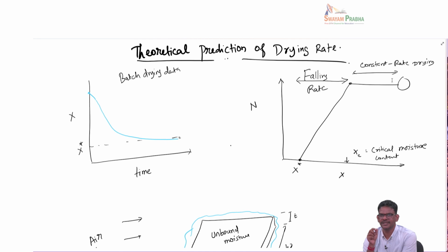On the other hand, if you are starting with a very cold object, then the time it takes to go from the initial temperature Ti to the surface temperature can be quite long. But in this analysis we have assumed that the initial temperature of the solid is very close to Ts, so the time required is not very much.